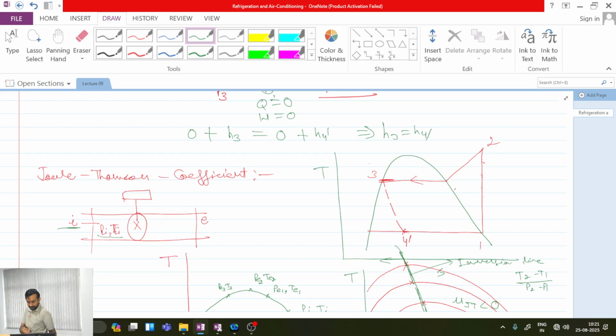Always we are decreasing the pressure, and along with the decrease in pressure, temperature should also decrease. Okay, so in the throttling device, temperature should also decrease, then only our purpose of changing the temperature from condenser temperature to evaporator temperature in the throttling process will be solved. Otherwise, this purpose will not be solved. I cannot move in a cycle. Okay, is this point clear?